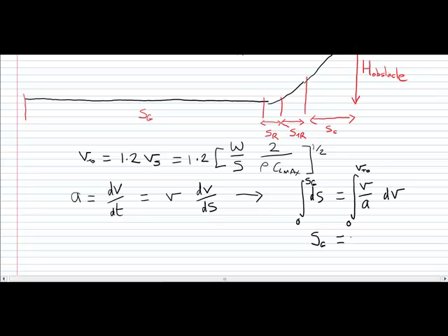But the challenge we have for the right hand side integral is that, because you might have a constant thrust being delivered by your aircraft, and because the drag force is a function of your aircraft speed as it increases in speed down the runway, this integral on the right hand side is not trivial.